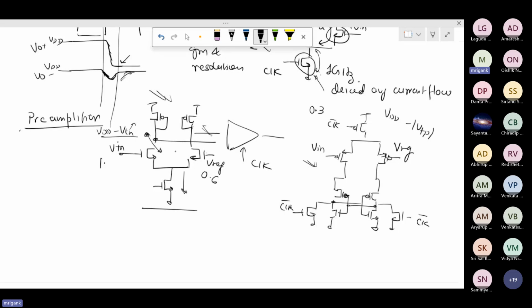But again, the preamplifier also here will work for what kind of levels. The signal here will work for Vin, which is Vref, higher than VT. So if the Vref in your application is fixed, suppose VDD by 2, or Vref is always a fixed value, suppose 0.7 volt, in that case I can use this. There is no problem because the Vref is fixed. Then the signal produced at the output will be fed to the next stage. But in applications like ADC, etc., the Vref also varies.